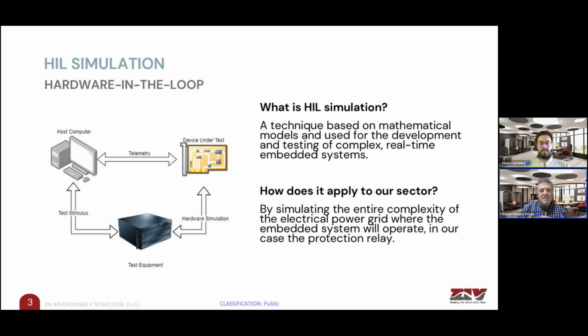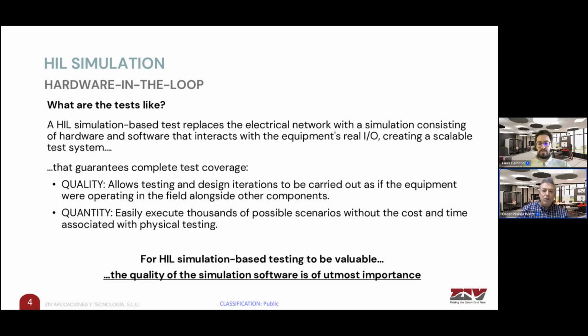Well, the thing is that our test equipment will be a powerful equipment with the capability of simulating the power system. So, in other words, our simulator will be replacing the real electrical network, will simulate the power transformers, the overhead lines, all the elements in the system, and that simulation will be interacting directly, in this case, with our protection relay.